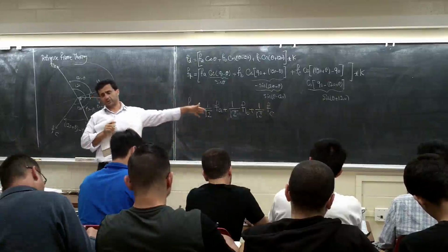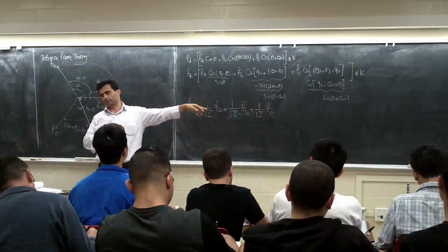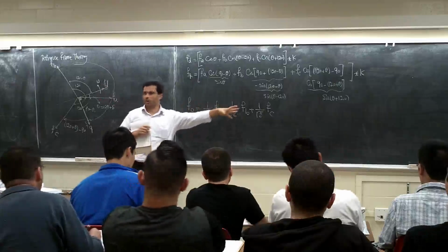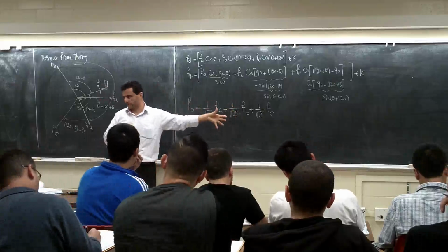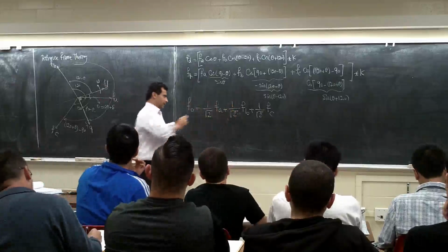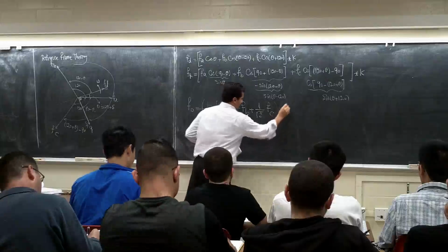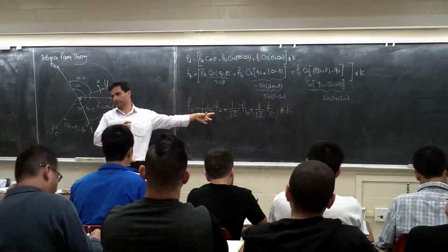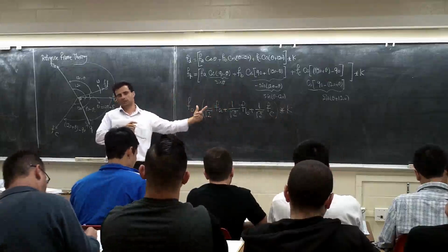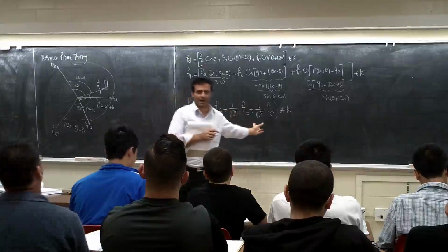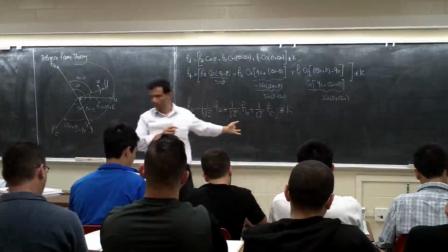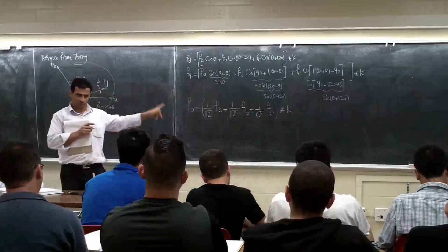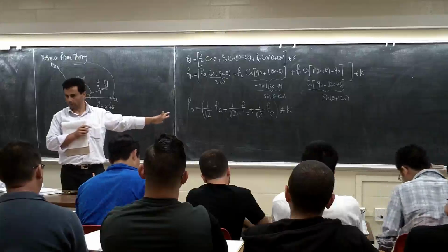You know, the system is symmetrical. How much is FA plus FB plus FC? It's zero, so it doesn't matter. I put the 1 over square root of 2 in front of all of them. I'll tell you later why I selected it this way. Again, this one times K. I call this one the zero component. Basically, the zero component in a system shows you how much your system is unbalanced. You know what I'm saying? If the zero component is zero, it means your system is perfectly balanced. But if it's not zero, there is something you have to work on.